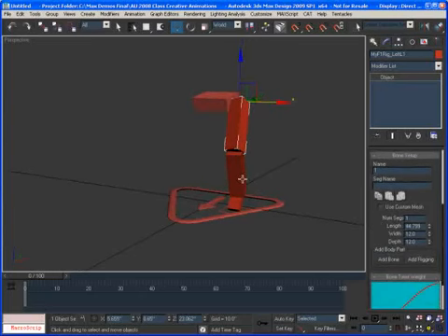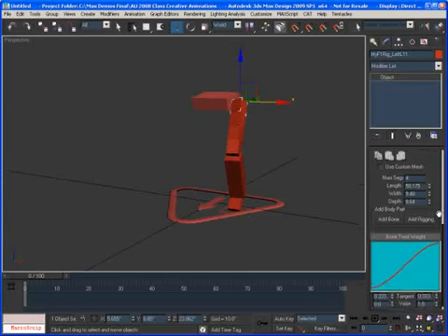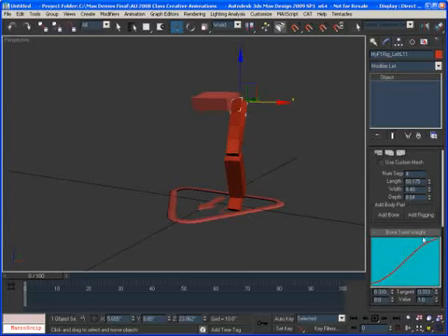So if you want to do any type of twisty bone, you can just increase the number of segments here to 3, or I'll make it 4. And you see that now this bone has 4 segments. You can define the length of the overall segments, and you see that it affects the overall length of the bone. I can define how big I want them to be, the depth, and all of that. But what's good about that as well is that you can define the threshold. I'm just going to move up a bit. So you can define the twist weight, so you can change all of that if you want that to be twisting more from the beginning or at the end, and you can change all of that with the curve here, and the value is how much the twisting is going to happen.